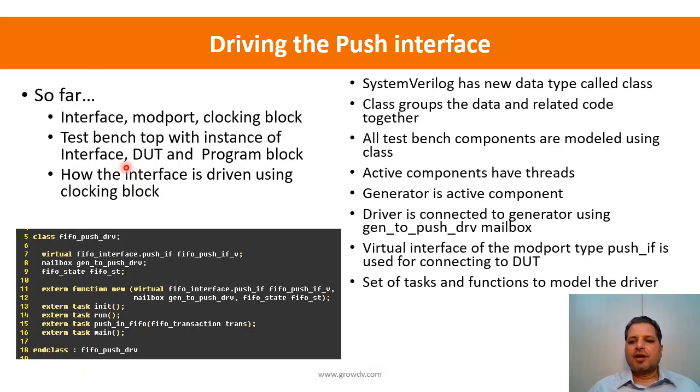So I am repeating a few things frequently over here because we are dealing with all the new things. So far we saw an interface, we saw a Modport which was a view to your signals, and we saw a clocking block which provided the information about when the signal is going to be sampled and when it is going to be driven.